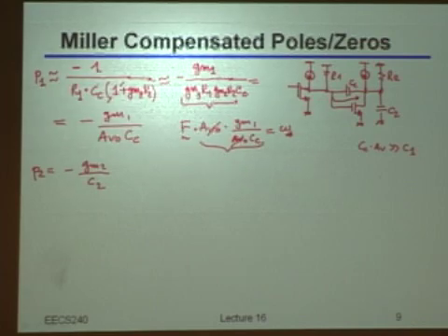Well, not really, because we're reasoning here in the S domain, right? There should be, of course, an S-domain frequency where you have the zero. But actually, it's the sign of the gain before the zero and after the zero that counts, right? If there is a zero with negative sign or with positive sign, that shifts the direction of the amplification.